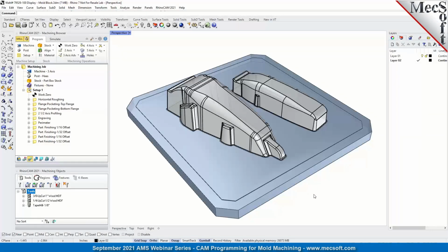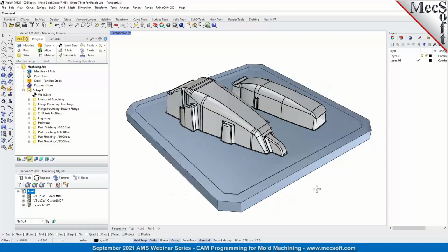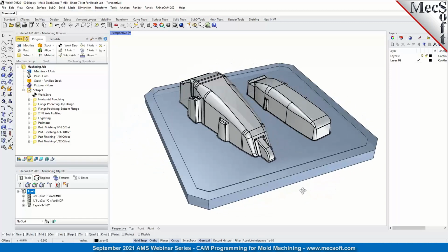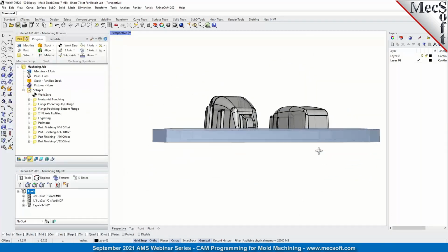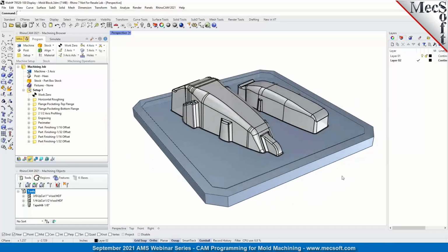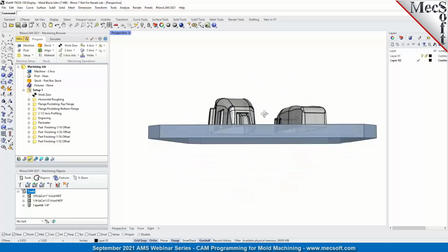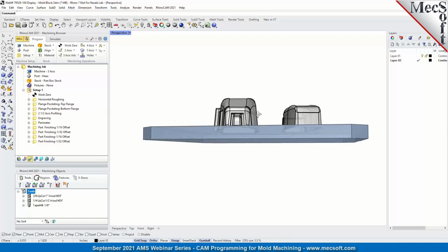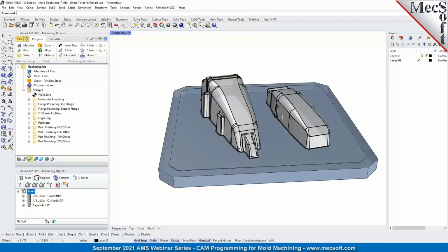So first up is the component from the Warren Group. They make thermoformed packaging and display packaging. And again, as I mentioned, you're generally machining a core side of the mold, and the thermoform plastic is going to be draped over that. So everything of concern here primarily is just the amount of draft you have on the cores to make sure that they come slipping out of that thermoform plastic, and you can see the draft here.